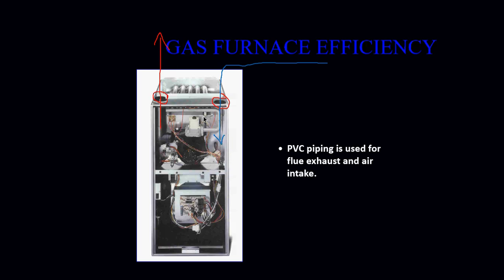So as this burner happens to be igniting, we are now introducing fresh air into the furnace to help with combustion. We are now ensuring that we are burning as much of the fuel as possible when the burner is operating, and any of the residual flue gases that have accumulated will now be exiting the flue pipe at a much lower temperature.